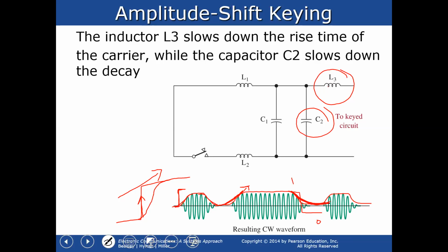The main advantage, or the reason why we're doing that, is to avoid requiring a very wide bandwidth, because with sharp edges I need a lot of harmonics, which means I need my carrier frequency and all the harmonics, like double, triple, 5 times the frequency and so on. That's what we mean by the higher harmonics. It means that you need to increase the bandwidth of your channel.